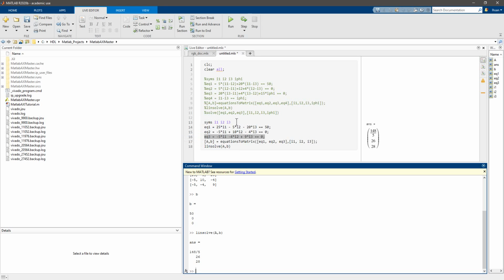So you define your variables first, which are the unknowns that need to be solved, then you define your equations in terms of those variables. Then you transform your equation system into a matrix form, then use the linear algebra tools to solve the equation system and obtain your unknowns, as you can see. So while you are studying, you can use this method to find the answers to homework questions or any circuit that you encounter. I hope you find this beneficial.